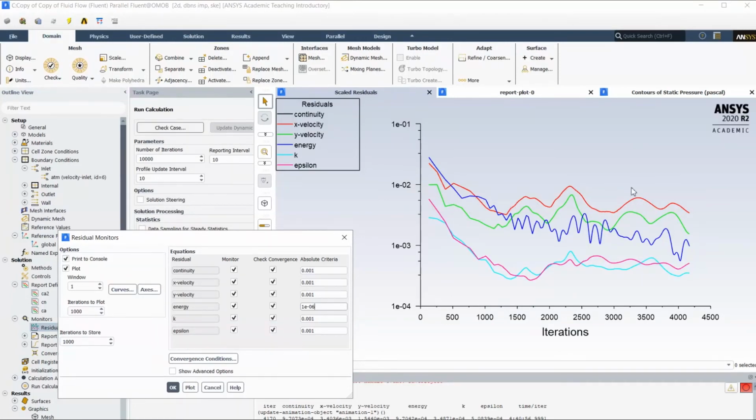I saw many times that there are several reasons when the residual can stay practically constant, a straight horizontal line, but it will not go down. It means that somewhere in your simulation there is a provocation of the flow changes and probably flow oscillations.